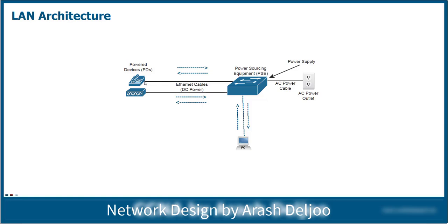Also, let me emphasize that we have some electrical methods for understanding whether the other device is a PoE device, a PD, or not. For example, you can apply a little voltage to the 2 pins of the device in the switch, and after that you can calculate the resistance of that device. If the resistance is a specific value, this means that it is a powered device, and if not, it is not a powered device.